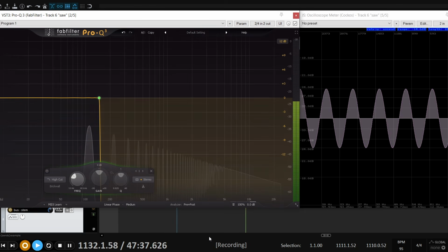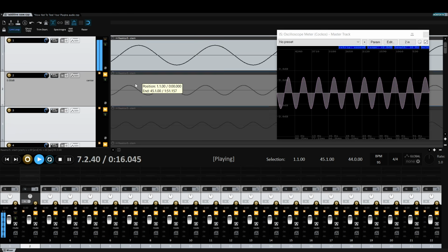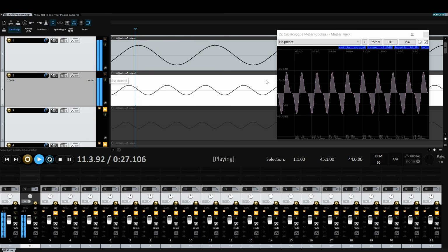But we can also go the other way and create a sawtooth wave additively by adding up a set of sine waves with the correct frequency and gain, and, importantly, phase. Here's a sine wave at 100 Hz. That's the fundamental. Now here's another sine wave at 200 Hz, twice the fundamental frequency, and also half the amplitude, so 6 dB quieter than the fundamental. When we add this in, the combined waveform gets skewed over to one side slightly. Still doesn't look much like a sawtooth, though.